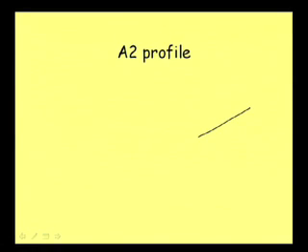Well, then let us see what will happen to the A3 profile or A2 profile. Here also we will be following the same understanding. The adverse slope means slope is like that, and critical depth, so SB is negative. The CDL line we always draw parallel to the bed, we are drawing critical depth line yc, and the yn here is imaginary.